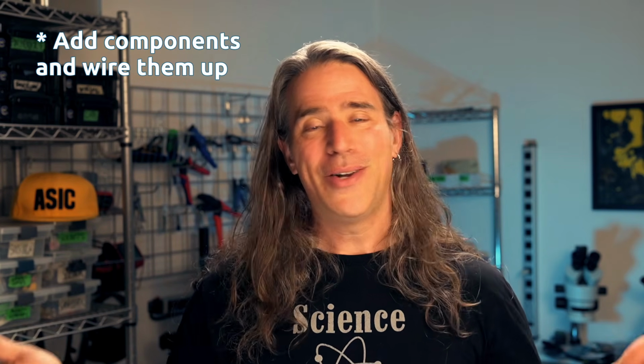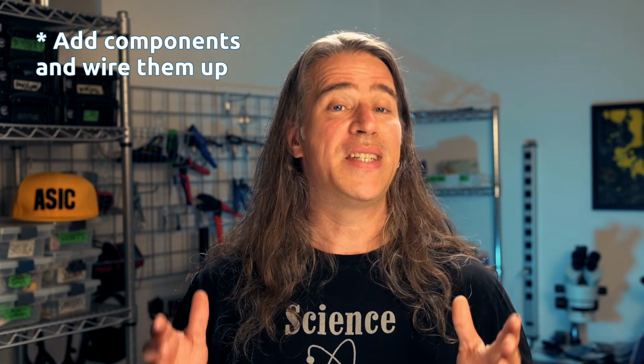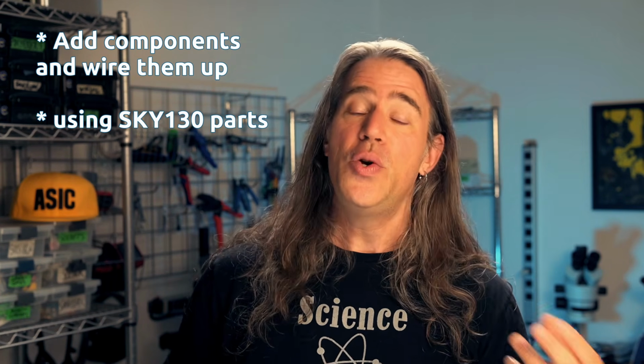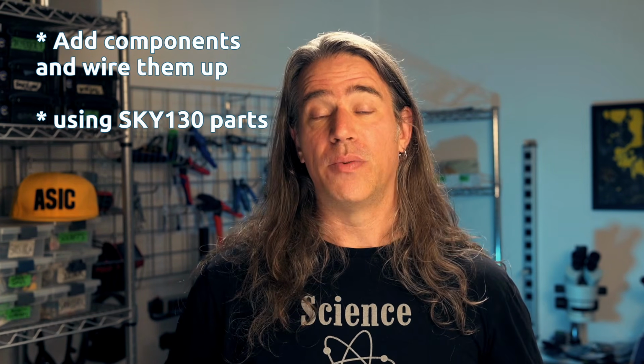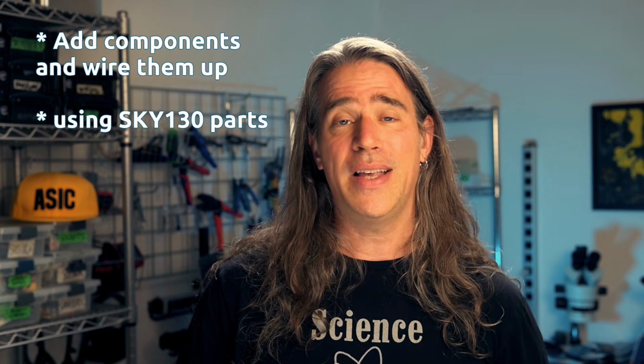You design a circuit using components and wire them together. Normal stuff. The components you use come from the Skywater PDK. In theory, you could actually get down there and even draw your own MOSFETs, but there are tons of design rules to obey, and people with great expertise and inside knowledge of the process have dealt with lots of that for you, so you're best off just customizing existing cells. The things you can count on in PCB land, like getting a resistor of a specific value, no.